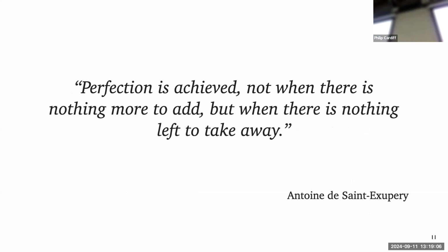So if you're interested in certain physical mechanisms, say lift and drag, you only need to include what directly impacts the prediction of lift and drag. You don't have to model, I don't know, the fire engines on the runway driving by and their effect on the wake. That probably isn't an effect you're trying to design for. So more does not necessarily mean better.